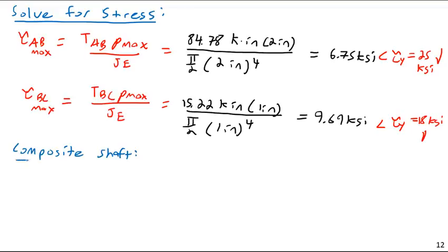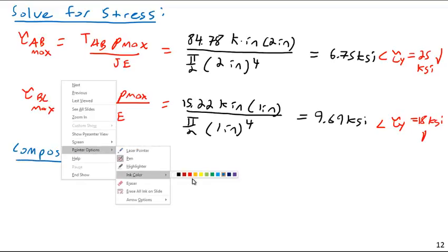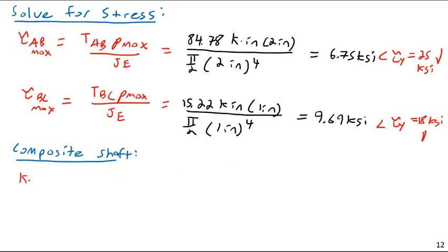So the real key to analyze these will be the following. The angle of rotation for material 1 must be exactly equal to the angle of rotation, or the angle of twist, of material 2.